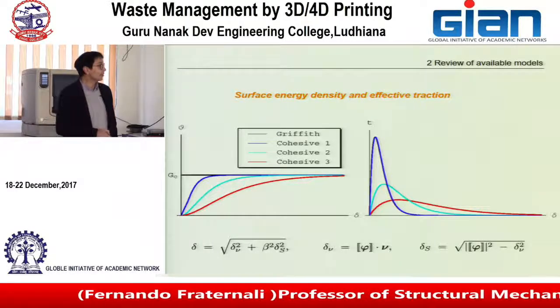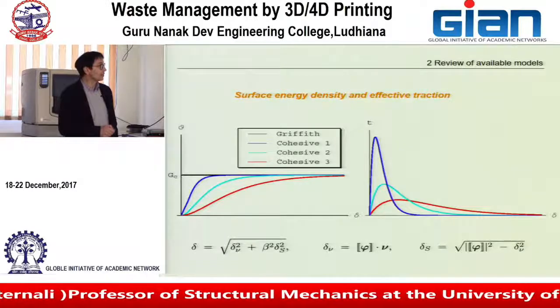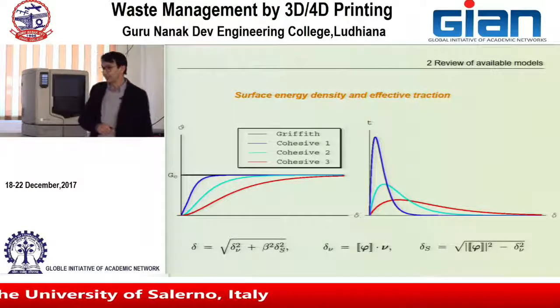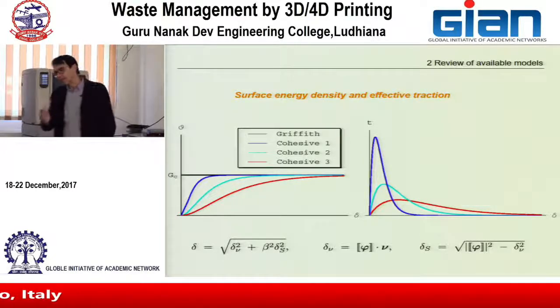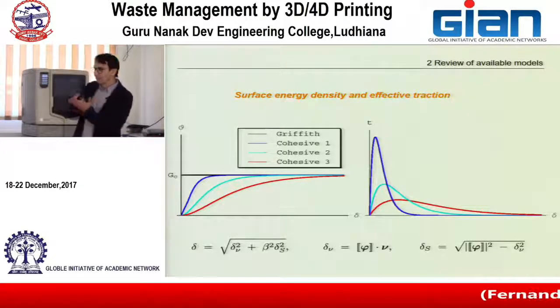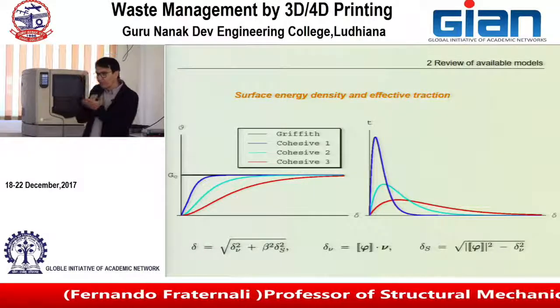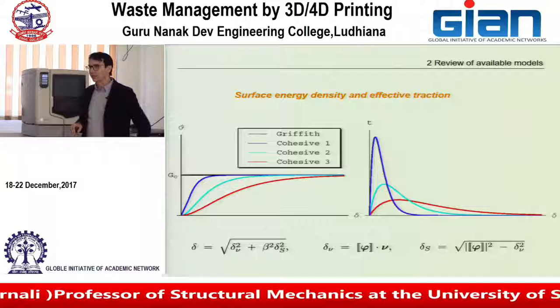Then you can have other models in which, on the contrary, the energy density depends on the crack opening displacement. Delta is the crack opening displacement, or the effective crack opening displacement, if you have mode 1 and mode 2, so you open the crack both normally and tangentially to the crack surface.